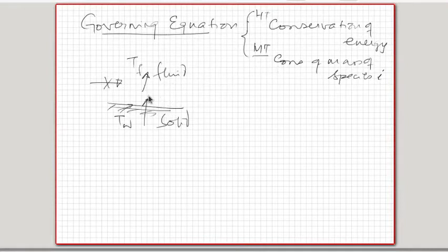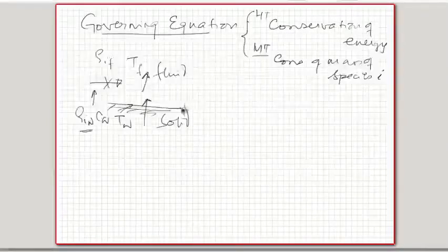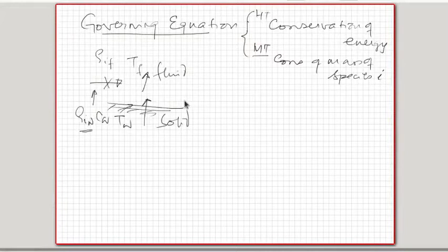Okay. Similarly, for mass transfer, if we have C wall as the concentration at the wall, or rho I wall is the partial density of the species at the wall, and rho I F is the partial density in the fluid medium, and if rho I wall is greater than rho I F in the medium, then the mass transfer happens by diffusion from the surface to the surroundings. For example, if I have a salt slab that is kept here and there is water stagnating on top of it, then the salt will diffuse into the water, because the concentration of salt or the partial density of salt at the surface of the salt slab is always higher than that in the fluid that is far away from it, and therefore there is movement of mass because of the gradient in concentration of salt.